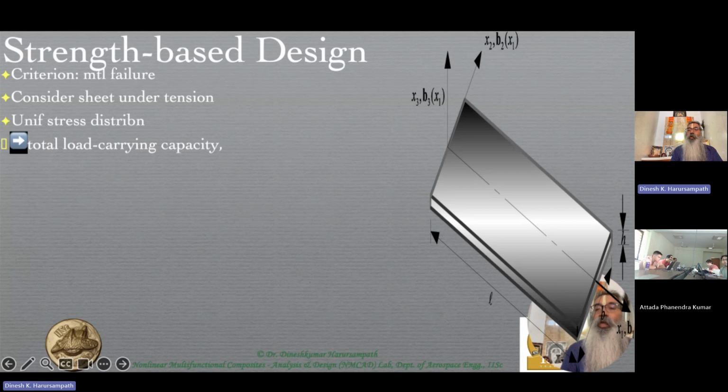When this is pulling apart, you slowly start increasing the value of the load so that it goes beyond the proportionality limit, beyond the yield of the material, and eventually to the ultimate tensile strength at some point, because of which a crack originates and a fracture takes place. Typically, of course, the specimen that you'd use in a UTM is not exactly rectangular like this.